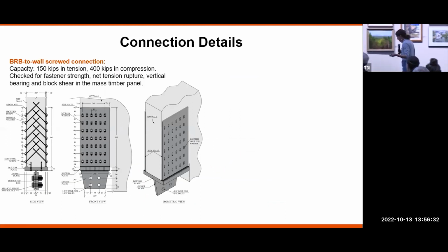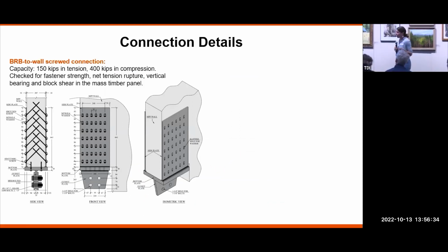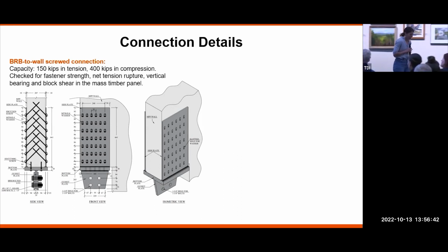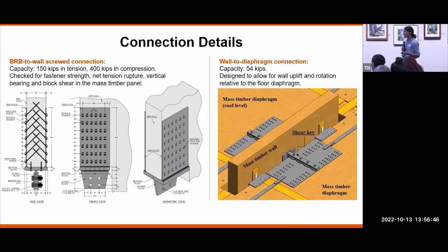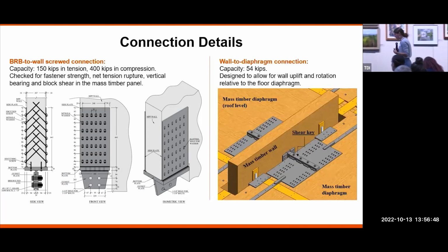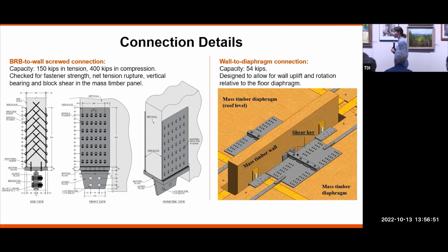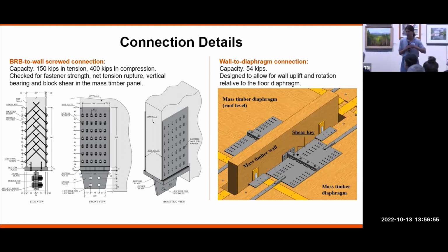Some things to think about. There are details here that we need to think about how to best model. So for example, we could model every inclined screw. We could come up with a continuum model for some of these connection details. We could think about maybe developing spring type models that connect the diaphragm to the walls themselves. And so there's a level of hierarchy and fidelity that needs to be thought about.